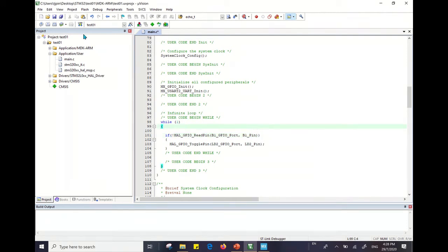Okay, let's save it. Click on save, and we use the build. There are two, build and rebuild. So we use the build. If this is the first time you're building, it will build all the libraries that are needed. If you already built one time and changed the code, when you press build, you will update all the changes that you have made instead of rebuilding the whole code, including the libraries. It takes a while. Okay, 0 errors, 0 warnings.